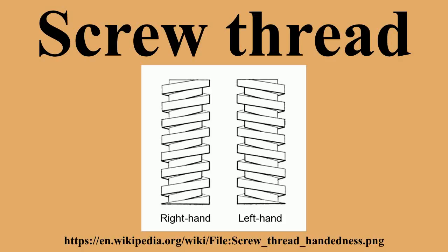Applications. Screw threads have several applications: fastening, with fasteners such as wood screws, machine screws, nuts and bolts; connecting threaded pipes and hoses to each other and to caps and fixtures; gear reduction via worm drives; moving objects linearly by converting rotary motion to linear motion, as in the lead screw of a jack; measuring by correlating linear motion to rotary motion, as in a micrometer; and both moving objects linearly and simultaneously measuring the movement, combining the two aforementioned functions, as in the lead screw of a lathe.